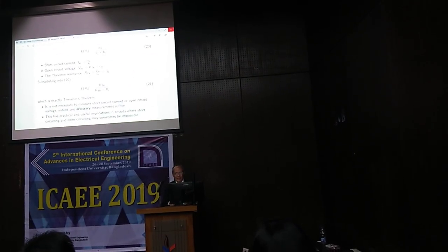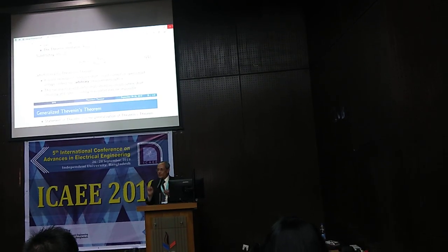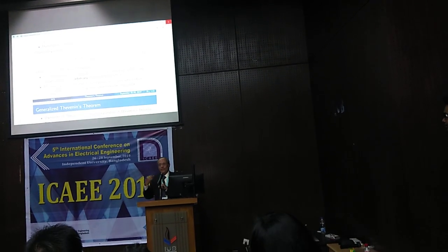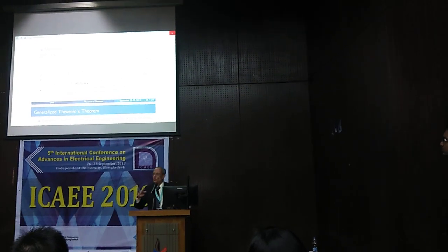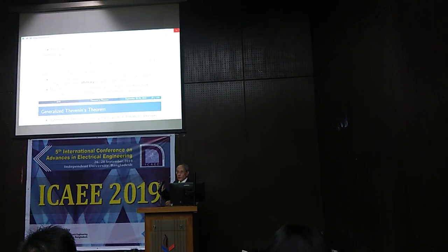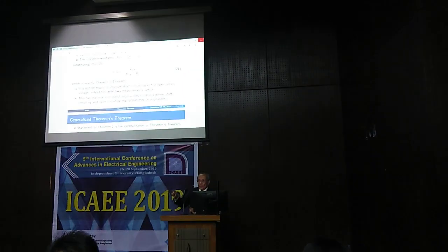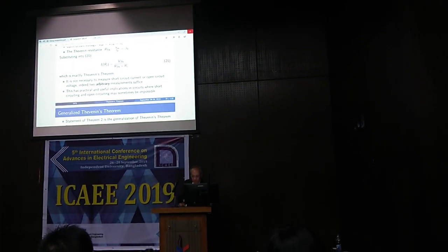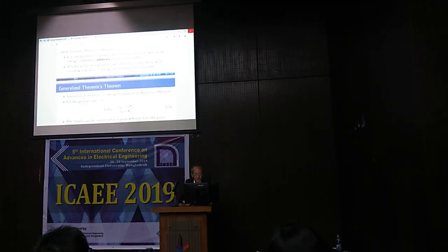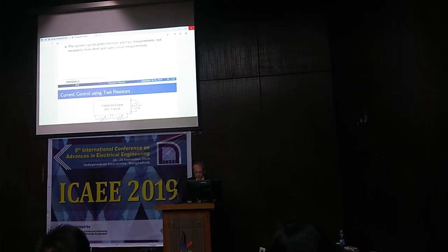So the interesting point here is that you don't have to short circuit anything, and you don't even have to open circuit anything. You can take 2 arbitrary measurements. From those, you can find the short circuit values and open circuit values. But many times you cannot short circuit 2 terminals in a circuit. All right. So now we start running.